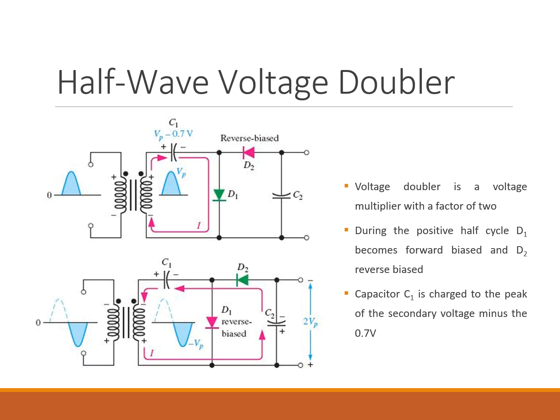It's one of the simplest and smartest ways to get 2 times the peak voltage from your AC source just using 2 diodes and 2 capacitors. Remember what we said, the inverse relationship between increasing voltage or decreasing current. So remember that you always give up something. Okay, so what's a half wave voltage doubler? This circuit multiplies the peak voltage, V sub P, by 2 at the output.